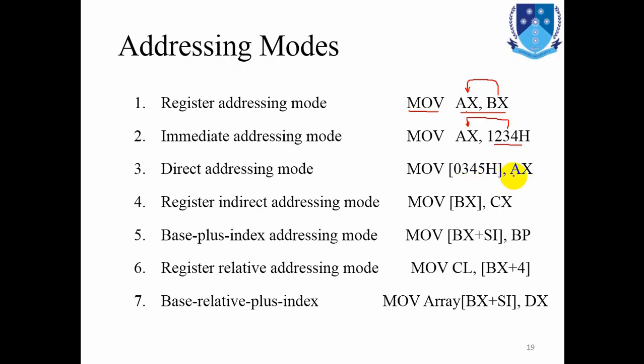So according to this instruction, the contents of the AX register will be transferred to a memory location addressed by 0345H.